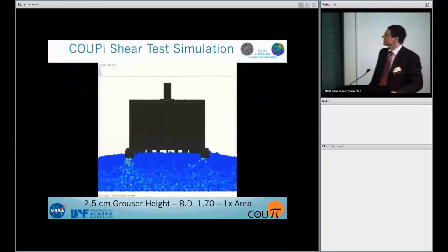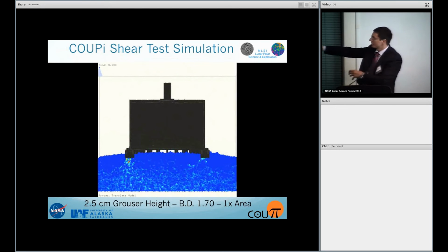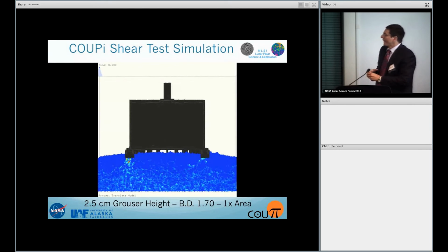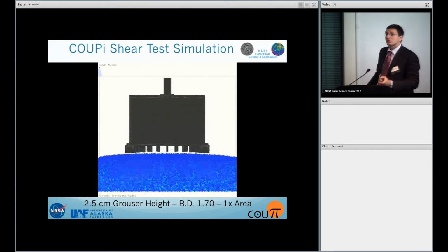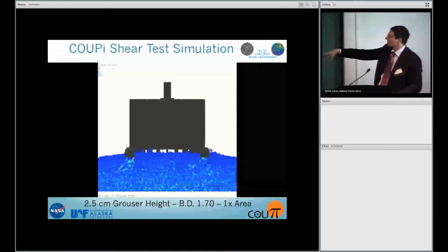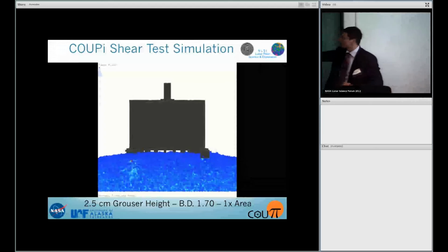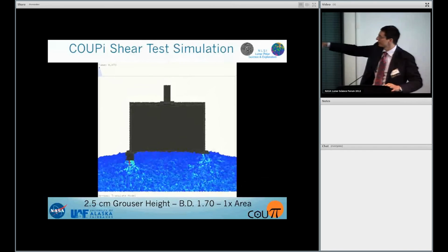This is the shear test, with the bevameter placed on the same soil. First it's pressed under a constant load into the regolith, and then it twists. Probably you won't see it because it's also just a slice, but then it starts rotating in this direction.